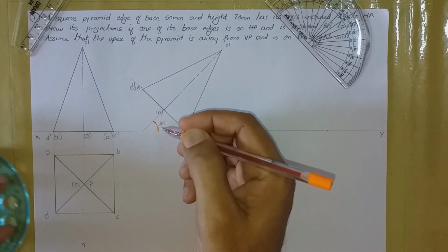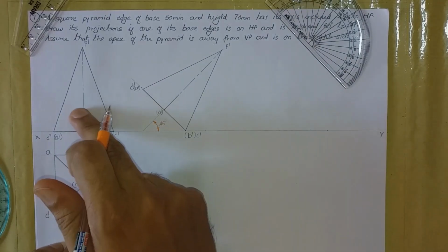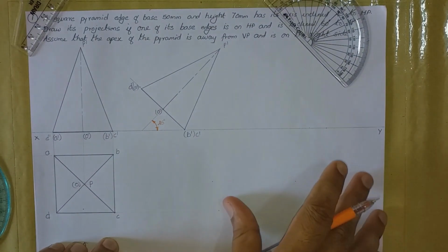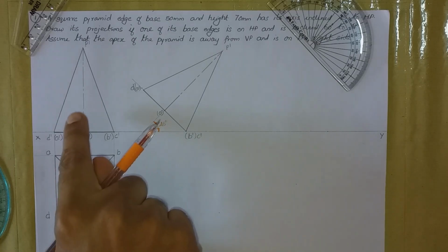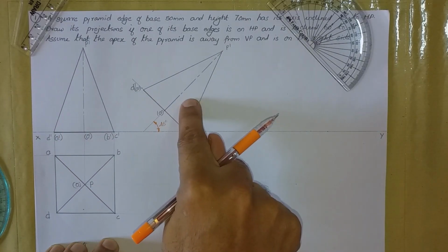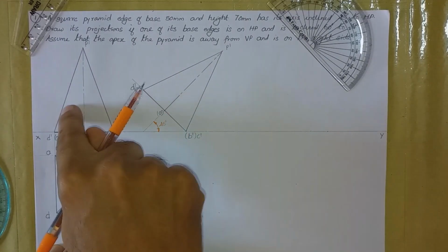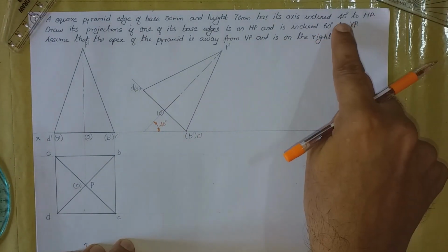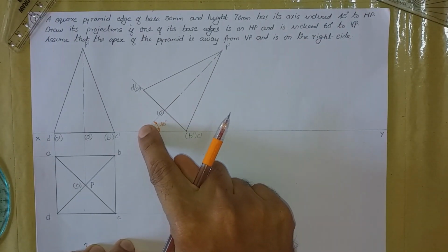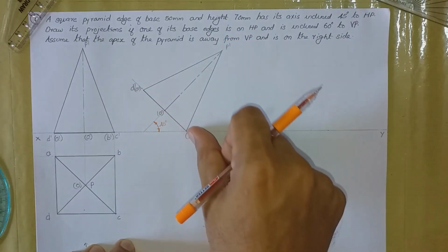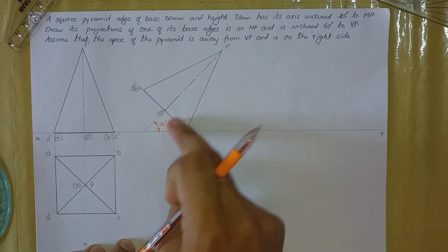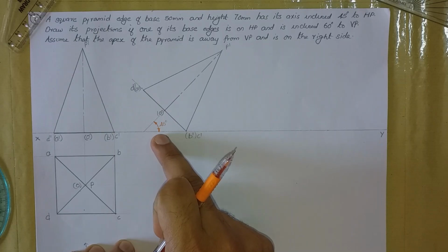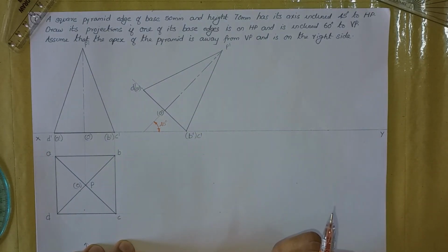Okay. So the difference between these two diagrams is only in the inclination. This is having only a change in the inclinations. Dimensionally, these two diagrams are the same. We have given only an inclination of 45 degrees for the axis. Here we have given an inclination of 45 degrees to the base, so that the axis is inclined at an angle of 45 degrees to the horizontal.